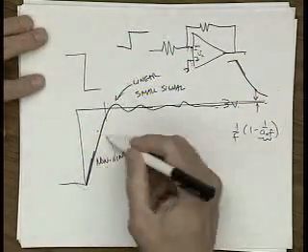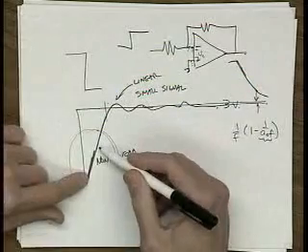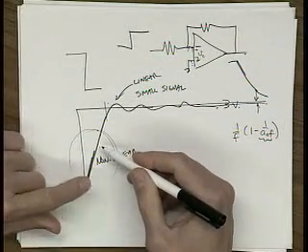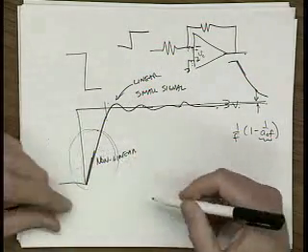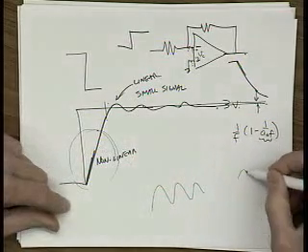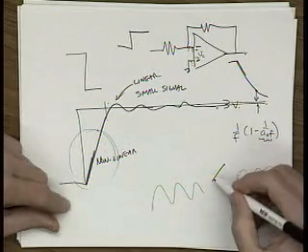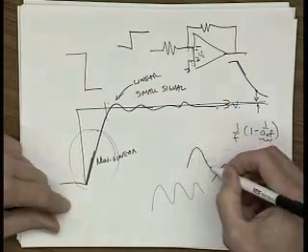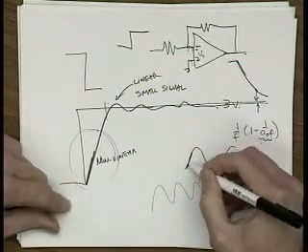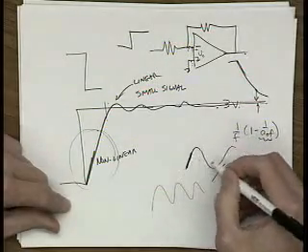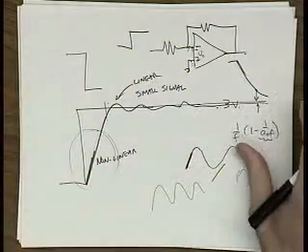This stuff's really bad. It's this region right here. This is generating harmonics and things like that. So this is really very nasty. I mean, you put in a sine wave, you don't get just a sine wave with a phase shift out. You get other sine waves out. Instead of looking like a sine wave, it has periods in here where it gets flat, and that's creating all sorts of harmonics.